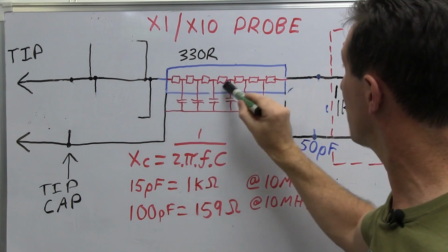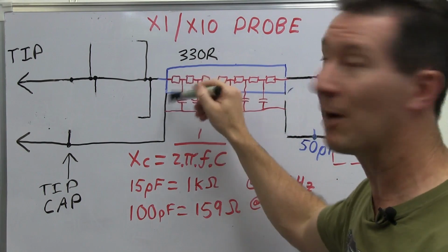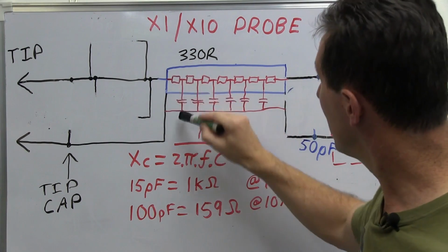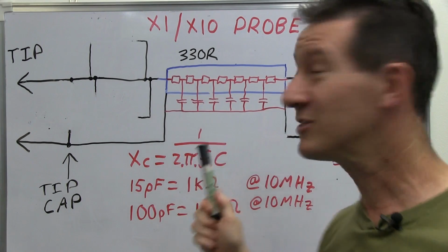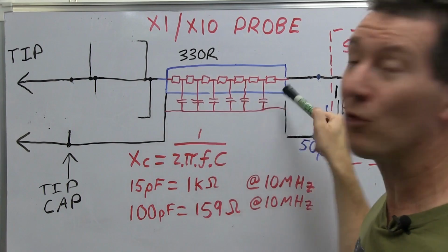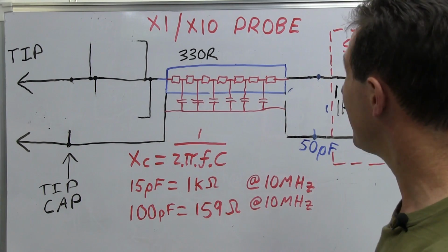So I've shown all the different resistors in there, and this is how you can simulate the thing using the lumped model like this. Then you've got the individual capacitances in here, and there will also be inductance in any model of a lossy transmission line like this, but I haven't shown any of the inductors.